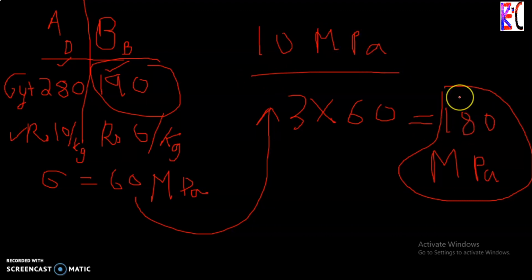So I could say that I am on the safer side. If I go for the maximum stress, it's also on the safer side. If I consider my lower stress 60, I am on the safer side. So you could also see that the margin between my selected sigma ut and the applied force is far different.